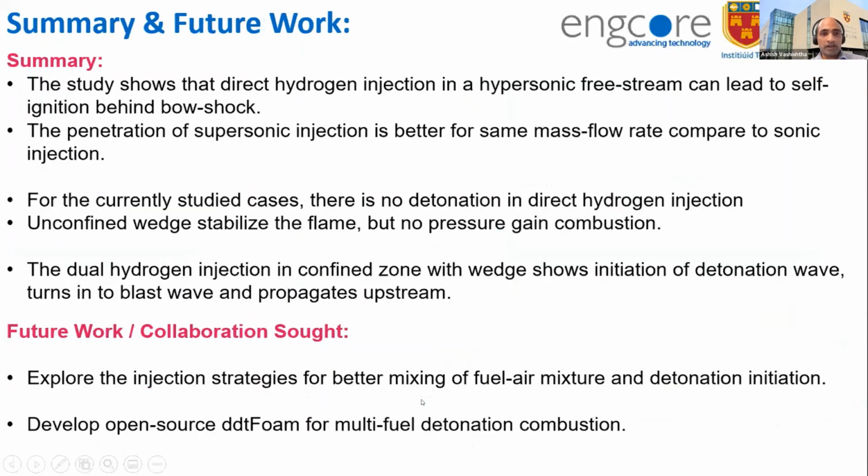So overall, this study shows that direct hydrogen injection in a hypersonic free stream can lead to self-ignition behind the bow shock, and the penetration of supersonic injection is better for the same mass flow rate than sonic injection. And there is no detonation in the direct hydrogen injection case. So the unconfined wedge stabilizes the flame, but there is no proper pressure gain combustion.